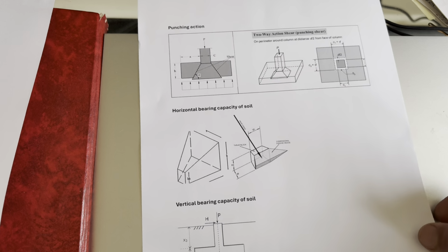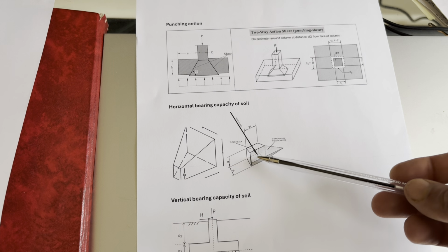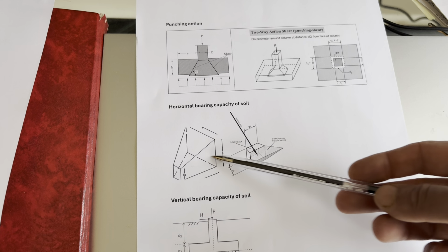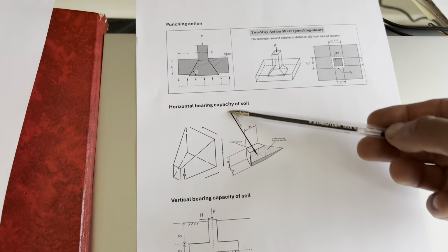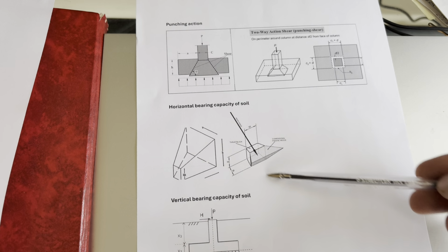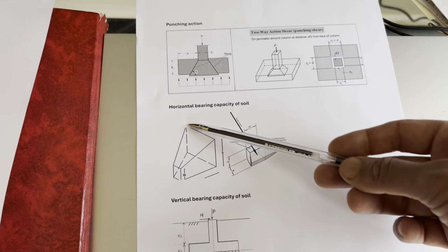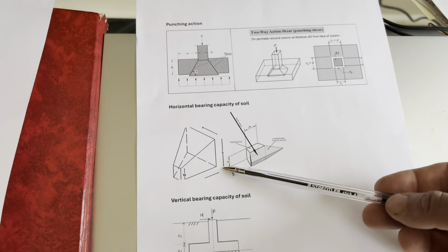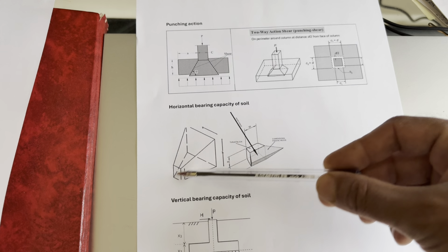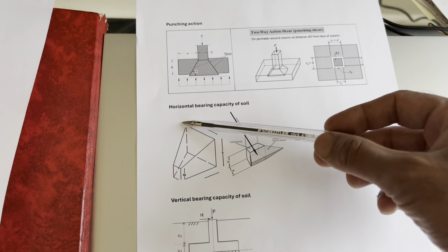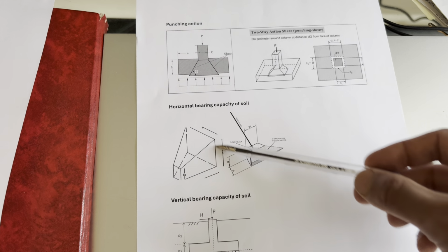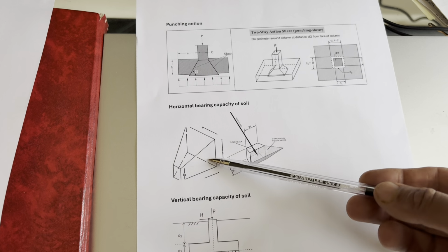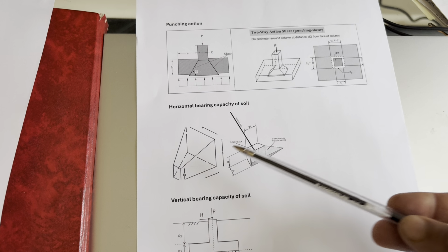So the main question here, when we're going to design a thrust block, let's say we have just something like a pad to transfer the loads from the piping system to the soil. In this case, the backside of this thrust block is the contact point with the soil. So we have a load here distributed on this back surface area, and if the load on the area is less than the bearing capacity of the soil, we say it is enough.